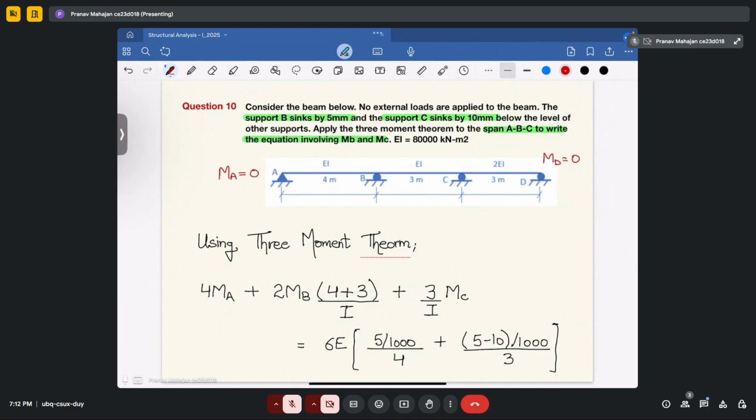The same thing we have then applied for a uniformly varying load cantilever beam, which has a propped support at the end B. Then we have solved another question, which has a continuous beam of 2 spans subjected to a 50 kilonewton force at the center of each span. Again, we have solved that using the force method.